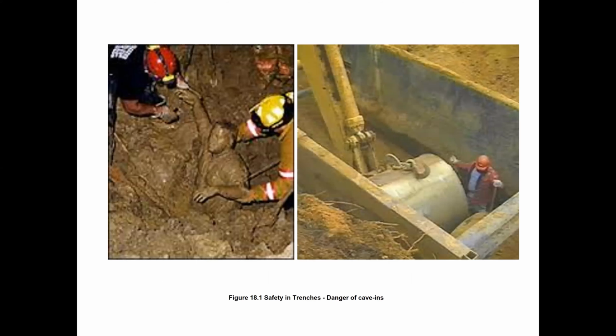In Saudi Arabia also, because of the sandy soil, there is a chance of collapse of these excavations. So the cave-in danger always exists. The backhoe is outside and people are inside. If we don't put in bracing to protect these trenches, the danger of cave-in is always there. To avoid this, we usually put in plates with bracing.